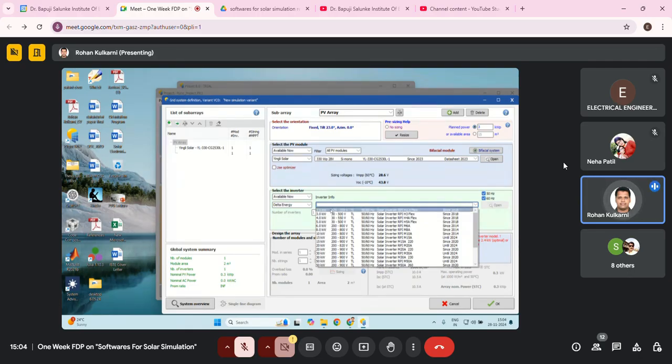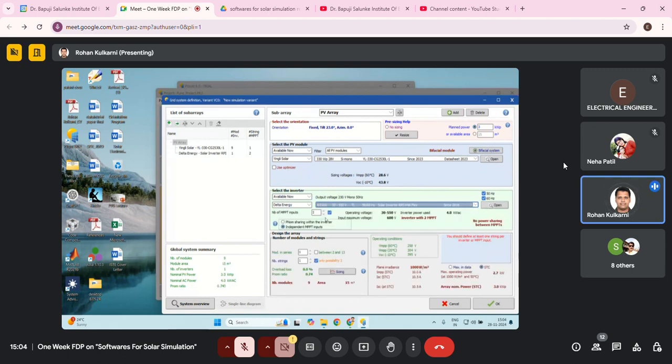So I would suggest selecting an inverter of 4 kilowatt. The reason is, whenever we add losses or some additional parameters, it creates some issues. Or sometimes it is possible in India especially that your input irradiation is more than 1000 watt per meter square. What is the standard test condition? Your input is 1000 watt per meter square, the temperature of the panel is 25 degrees Celsius, and there is no shading.